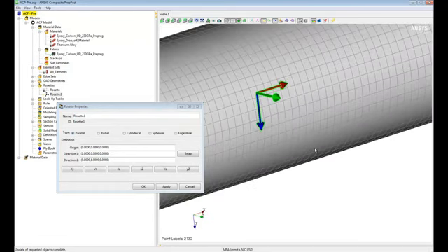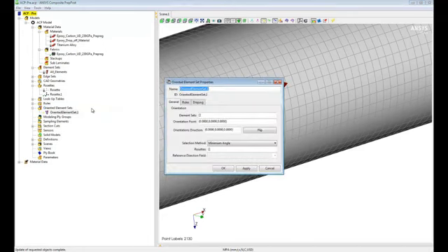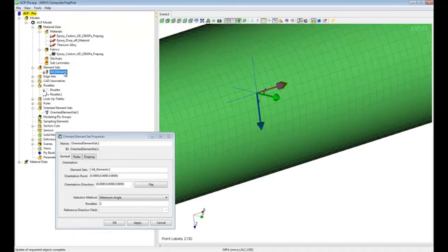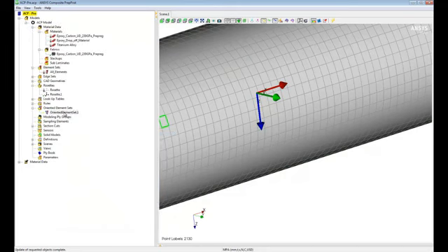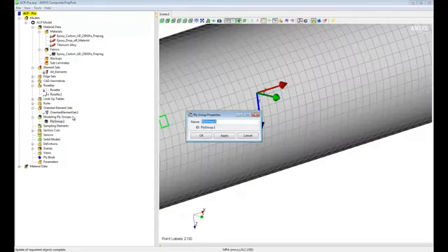We do that using a system of rosettes. In this case, we are just going to use one aligned with the axis of our cylinder, and this one will now be used to create what we call an oriented element set. Basically, that's a group of elements on which we are going to define the orientation. So we take the element groups, we define the normal, which could be one way or the other, all depends on how you want to set up the plies, and we use a given rosette. When we do that, we've basically defined the zero orientation that will be used for subsequent definitions. You see the yellow arrows defining this orientation.